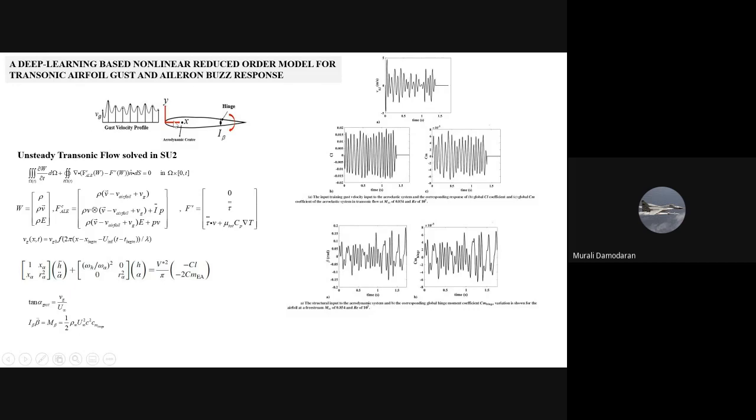So as a gust is there is a transonic flow, external transonic flow, and we superimpose a gust, which is vertically rising air, and when it goes over this airfoil, this flap may start to move. The motion of that flap is controlled by this angle beta, which is given by the moment of inertia times the second order differential of beta equal to the torque.